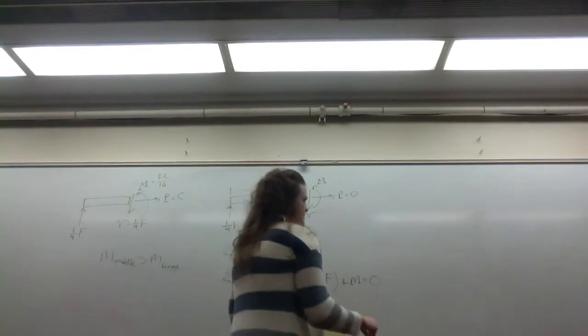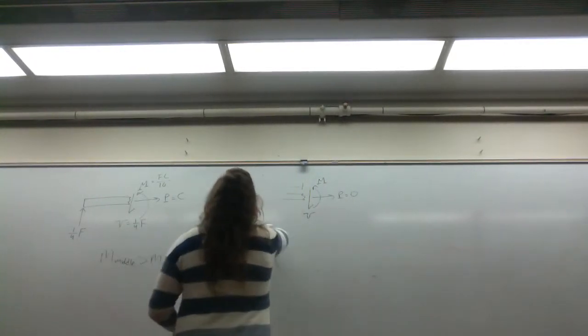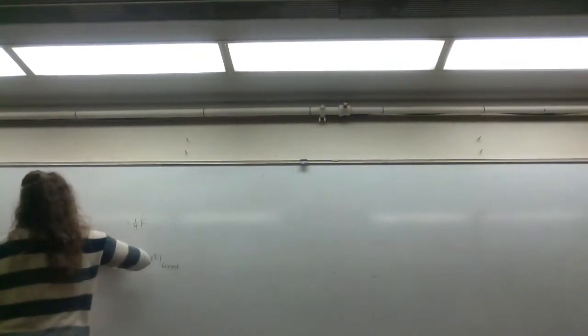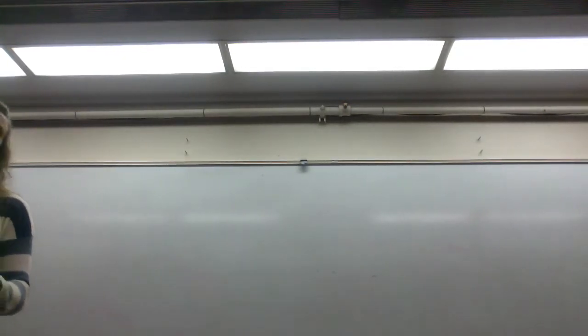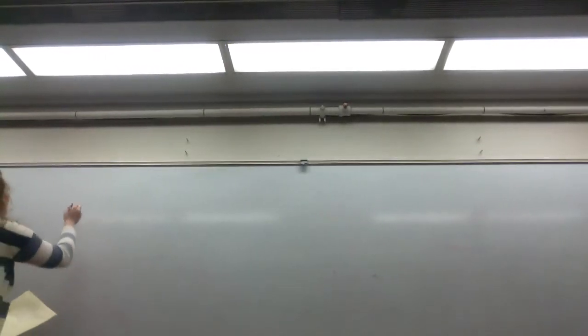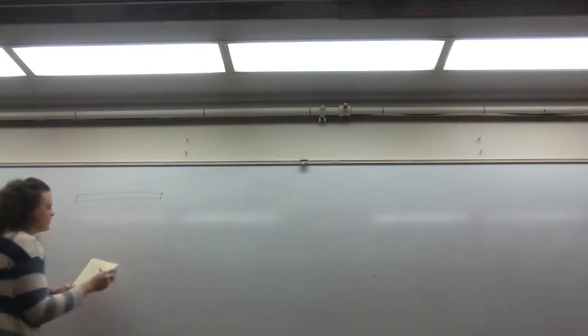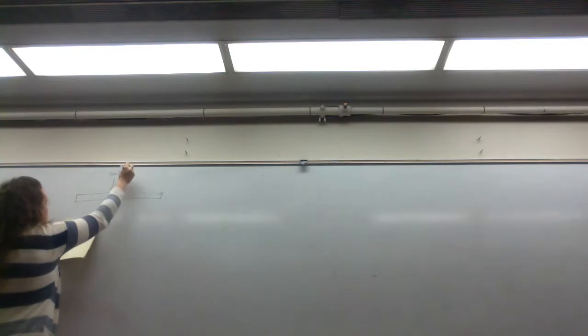So if we work through this problem, a beam with two loading positions. We have a point force of 80 pounds at point C, an applied moment at point D. Right? So your first step, get out your calculators. Your first step is to solve for your external reactions. Okay, so if I draw my applied loads,